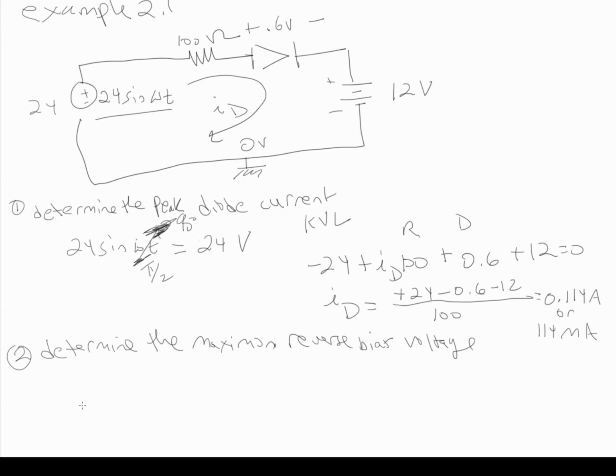And so if we drew this here, plus minus, and we have our resistor, and then our diode, and then our power supply, which we said was 12 volts. And so if we're looking at Vs here, then it's going to follow something like this. And so this would be plus 24, and down here would be minus 24. So we'll say this point becomes minus 24.